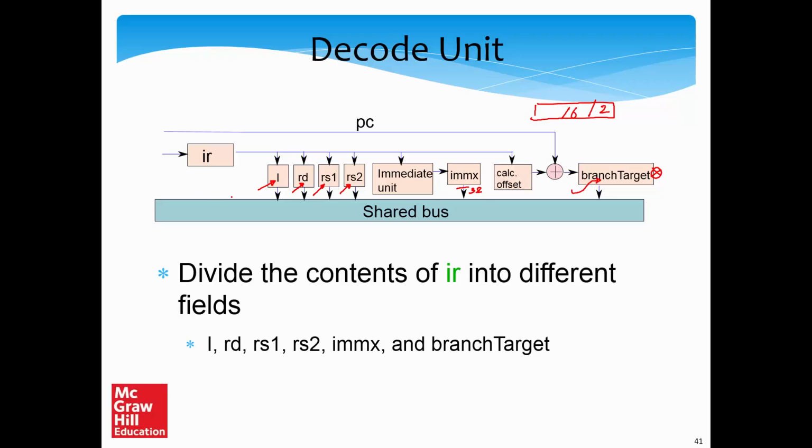All of these registers are connected on a shared bus. What is a shared bus? So a shared bus is basically a set of copper wires to which all of these registers are connected. But it is not the case that all of them are feeding their data to these copper wires, right? So then it will not work. So by default, these links between the register and the bus are actually turned off or they are open circuits. But it is possible for us, as we shall see in the next few slides, to occasionally read these registers.